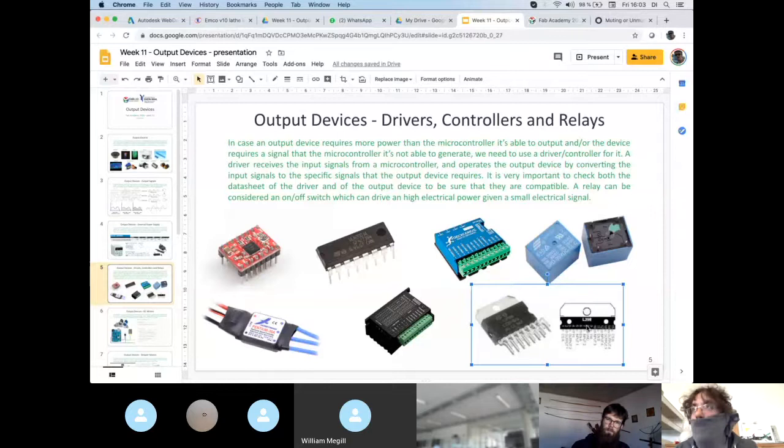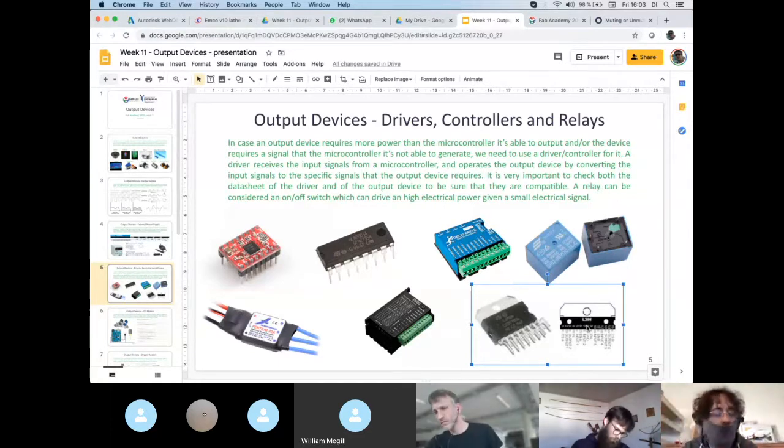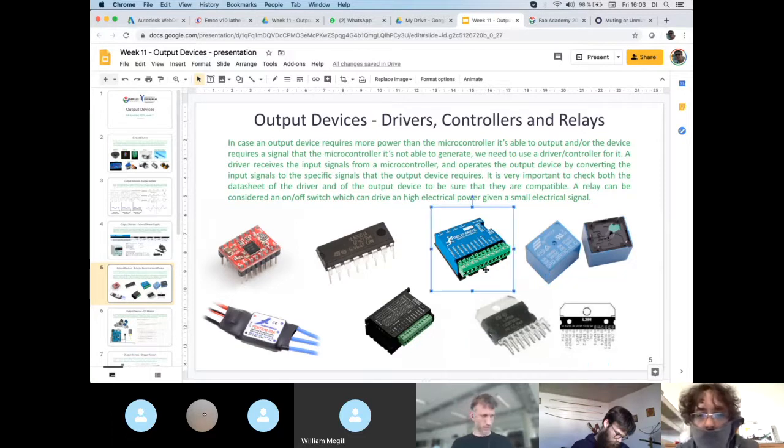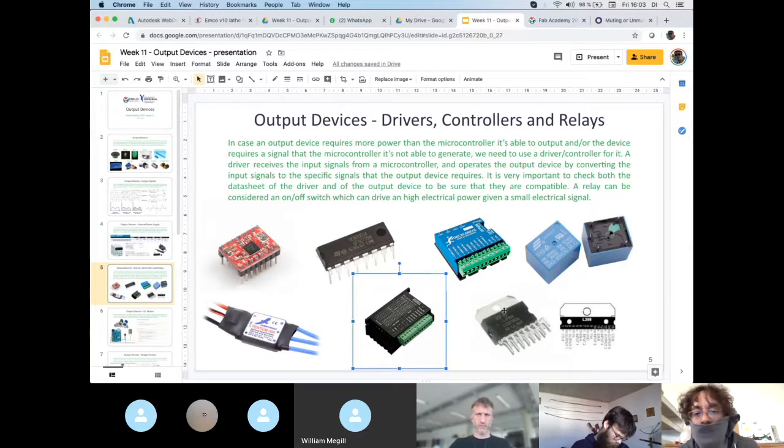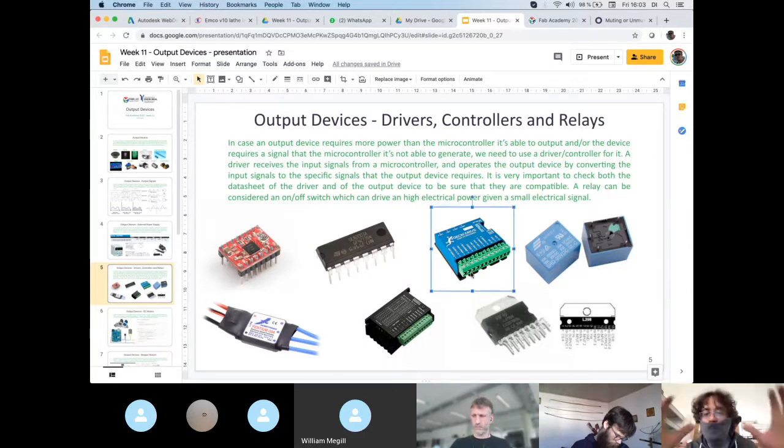And then you can create your own stepper drivers with this, adding interface logic to the microcontroller, adding capacitors, adding diodes for protection, optoisolators, and so on. So what I want to say is that the H-bridge is actually the core of the stepper drivers that you have over here. And the stepper drivers are just H-bridges with some other nice additions around them.